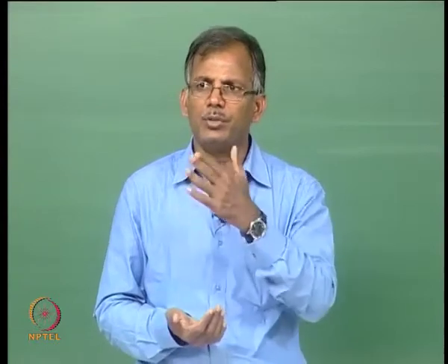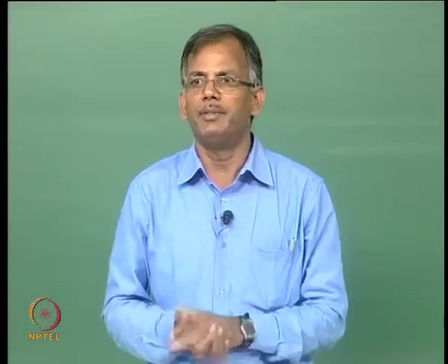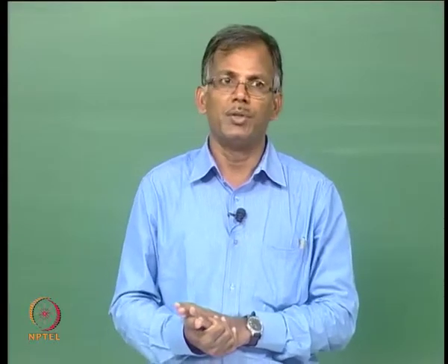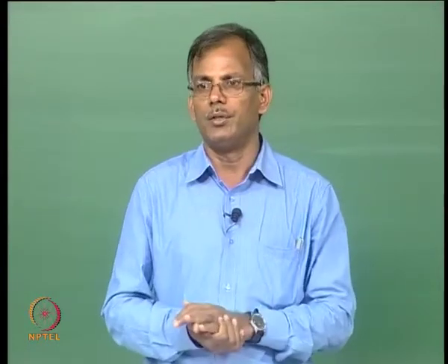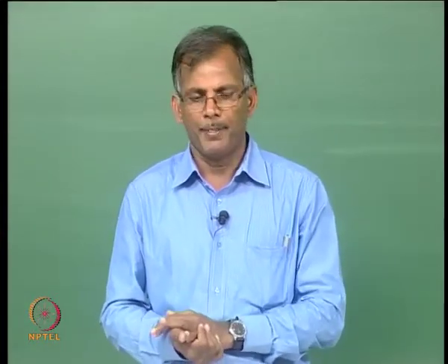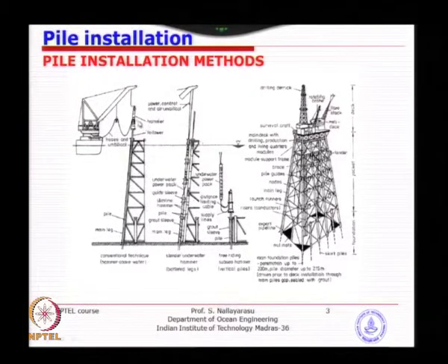I think we discussed this. The larger the gap the better, but larger is not too good for design purposes. We discussed load transfer. So, typically 1.5 inches, sometimes 2 inches, very rarely, is given, so that we insert this pile, it goes through into the seabed, and then the self penetration happens.